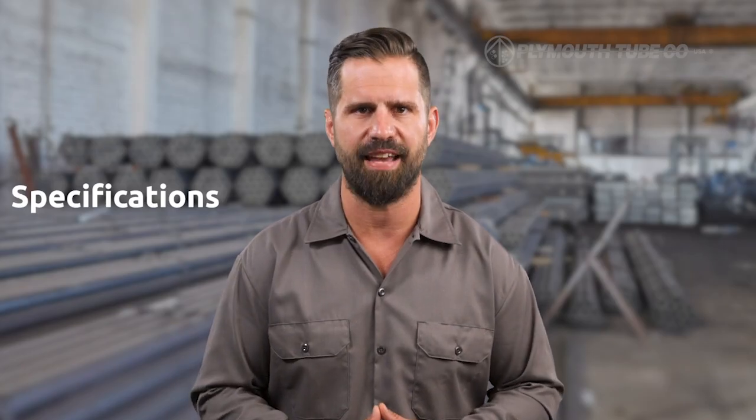There are 4 different types of ASTM standards. Test method, which provides definitive testing procedures to produce test results. Specifications, which are an explicit set of requirements a material, product, system, or service needs to satisfy. Guides, which are additional information or options which do not recommend a specific course of action. Practice, which is a definitive set of instructions for performing operations which do not produce test results.